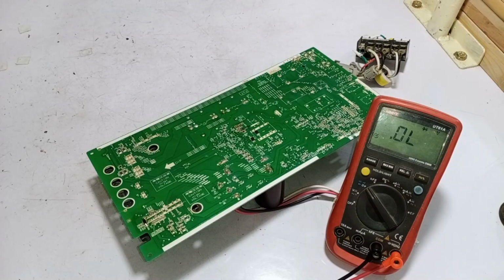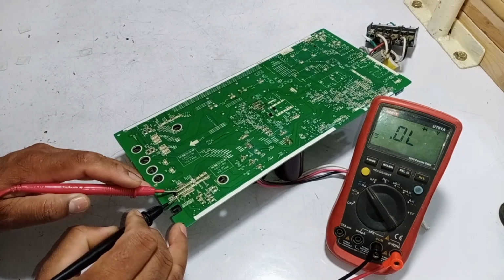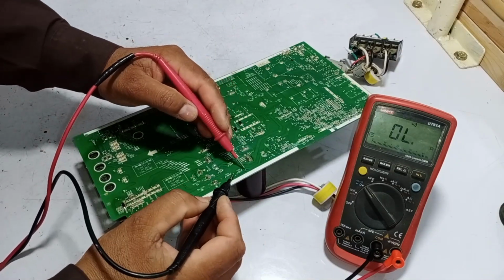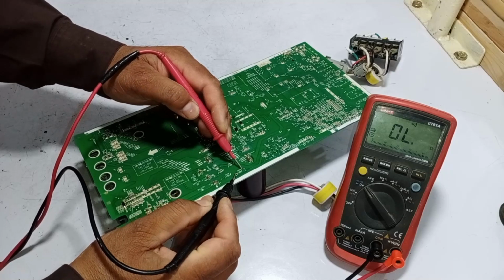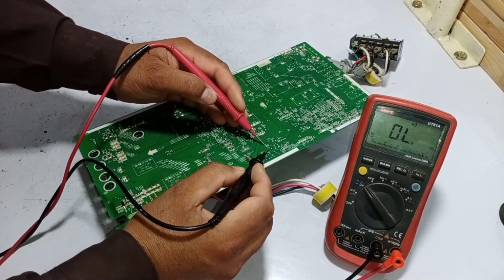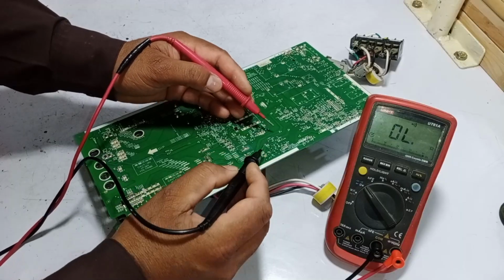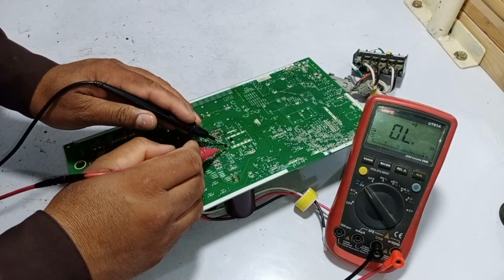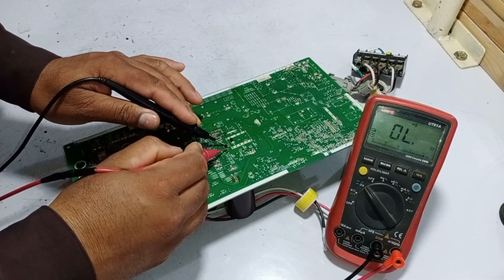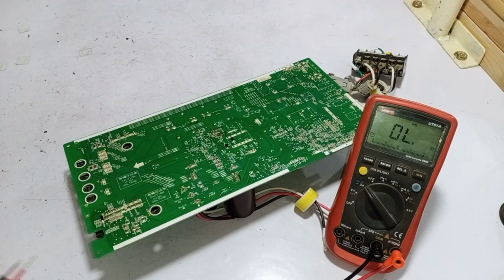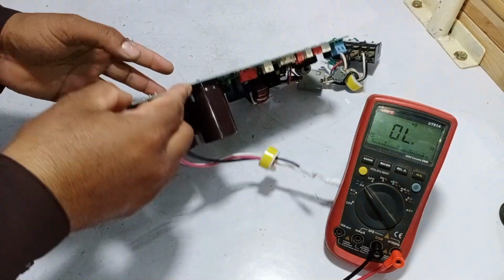Now the PCB is fully ready from every aspect, so let me test it and show you what we have done. First, I replaced the diode, and now it shows 0.466 volts during testing. Next, I checked the capacitors in continuity mode, and as you can see, the beeping sound has completely stopped. This indicates that there are no longer any continuity issues with the capacitors. Additionally, the diode displayed a proper value and stopped conducting, which confirms that it is working correctly. This indicates that the system is now functioning properly without any problems.